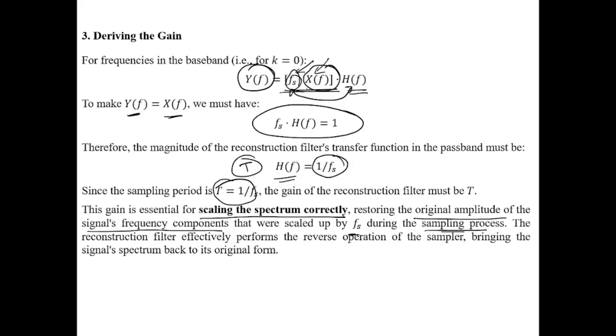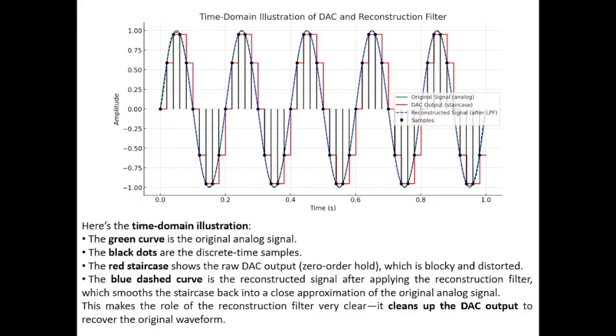The reconstruction filter effectively performs the reverse operation of the sampler, that is the sampling, bringing the signal spectrum back to its original form. This is the main important point over here.